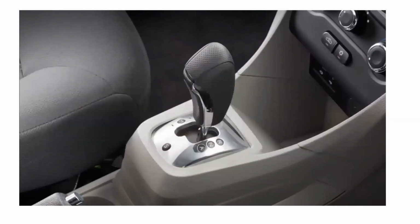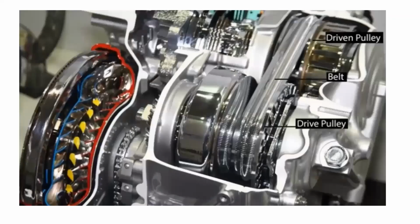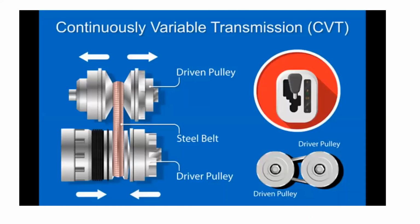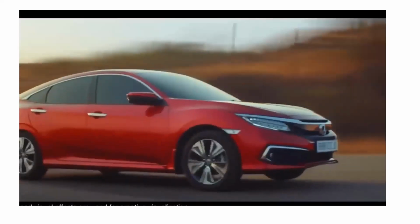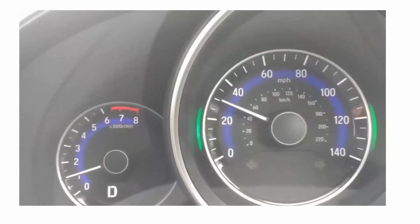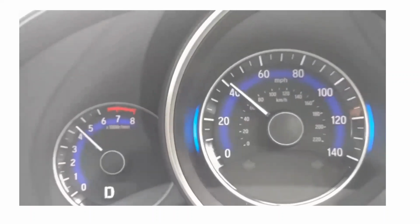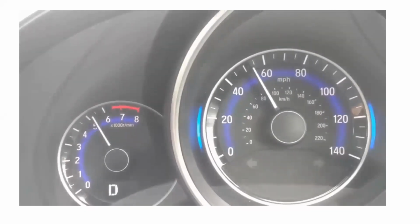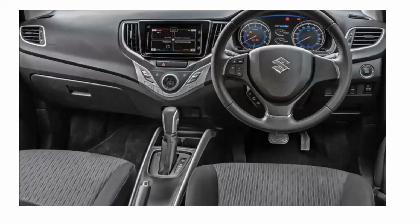Moving on, let's talk about CVT or continuously variable transmission. CVTs are one of the most refined automatic transmissions. The CVTs use steel pulleys and a belt that can generate infinite gear ratios. This means that there really are no gear changes as such, leading to smooth, seamless power delivery. This type of transmission is very quiet too, and is widely used in gearless scooters in India. However, CVTs can feel a bit elastic when you drive them, especially when you notice what is called a rubber band effect. Premium cars like the Hyundai i20, Maruti Baleno use these types of transmissions.